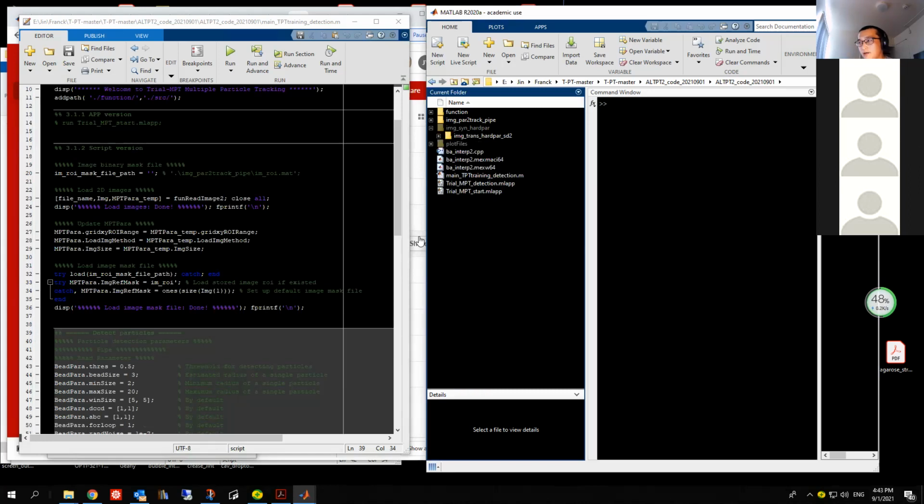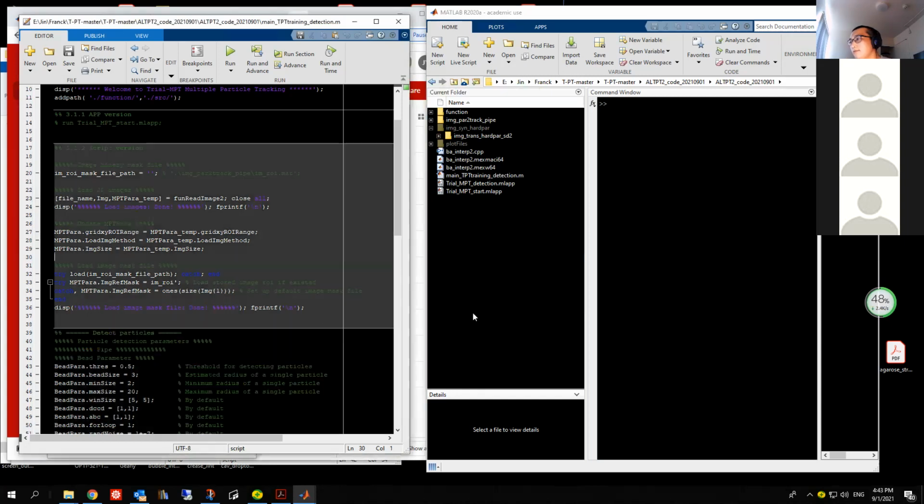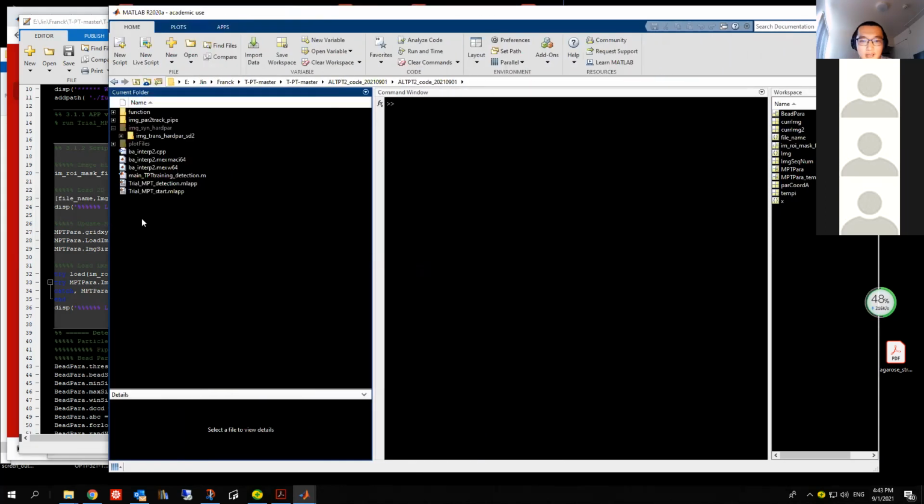Usually 2D is super fast. The computer I showed you is not that powerful, the RAM is only 16 gigabytes, so you should have similar speed. Should we select parallel computing? If that's possible, that would be better. Here you can still see my screen, right? Okay, so open your parallel computing setup. In your MATLAB menu at the top, you can see there's the parallel option, and there's the parallel preferences.